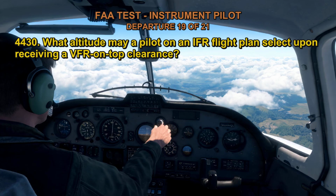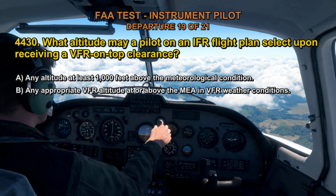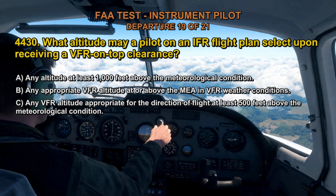4430. What altitude may a pilot on an IFR flight plan select upon receiving a VFR on top clearance? A. Any altitude at least 1,000 feet above the meteorological condition. B. Any appropriate VFR altitude at or above the MEA and VFR weather conditions. C. Any VFR altitude appropriate for the direction of flight at least 500 feet above the meteorological condition.